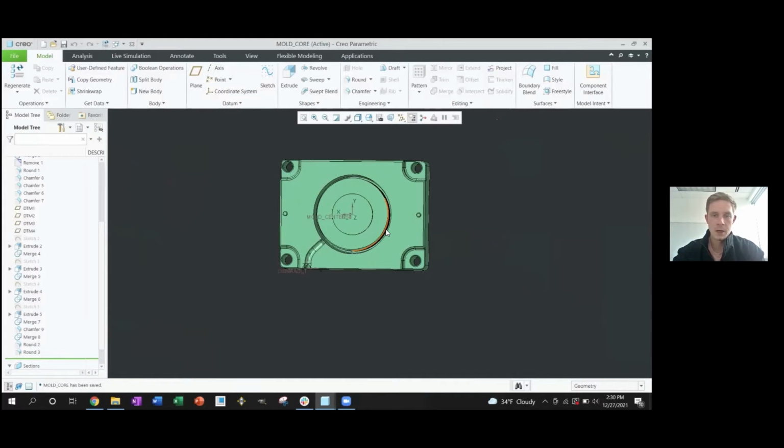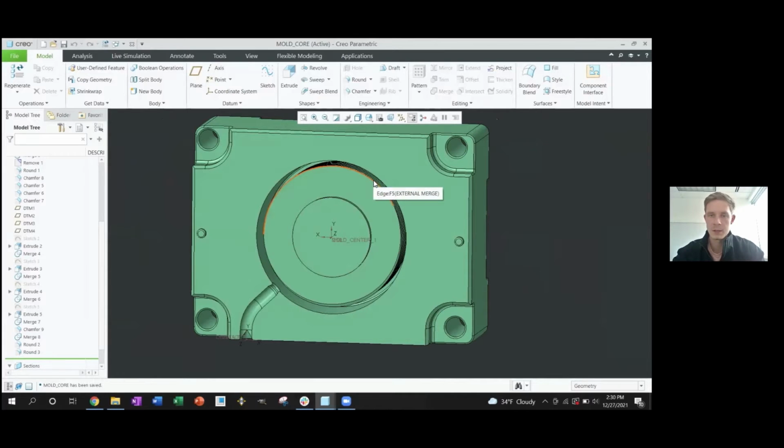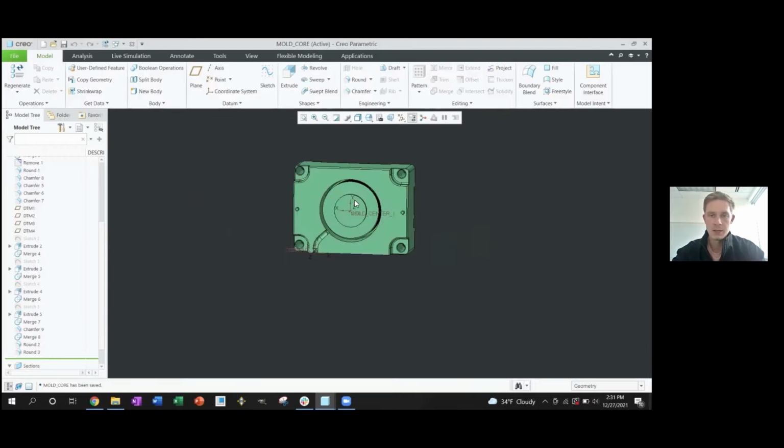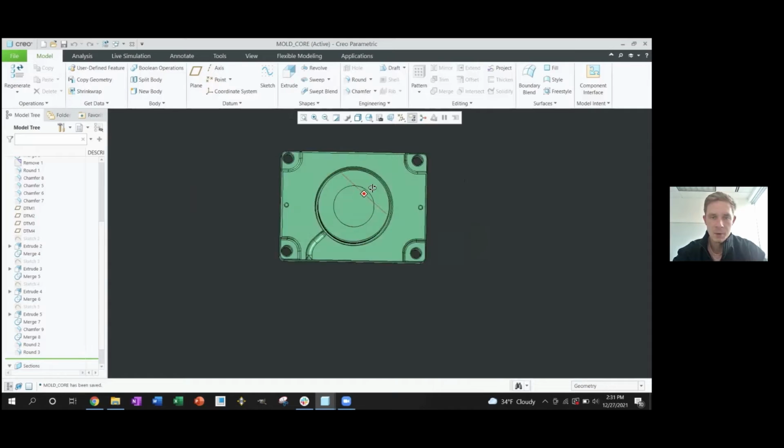So at Fortify, we like to attack that by turning this threaded section into a removable insert so that you can inject your part on the machine and then eject the part off the core off the machine. That really enables you to be ejecting a part while you're shooting your next part and really speed up your cycle time during this molding process. It also allows you to avoid really cost ineffective options of different metal cores that have all sorts of bells and whistles, but they don't really marry well with the prototype philosophy that we have, being agile and getting parts quickly.